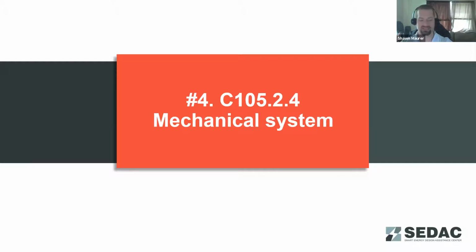If a paint on UV protectant is used, it needs to be reapplied every couple of years at a minimum. And that doesn't usually get done. It's not highlighted to the building owner. So the code has specified that there does need to be a jacket system that is removable on that insulation to protect it. And as we noted, there are systems out there specifically designed for those refrigerant lines.